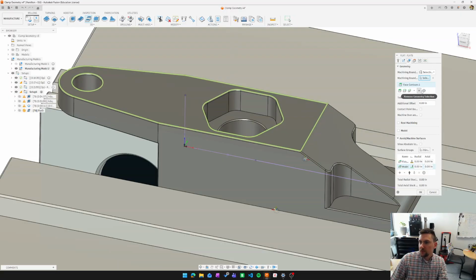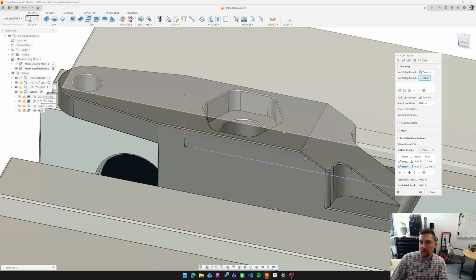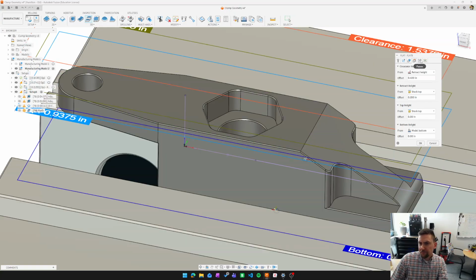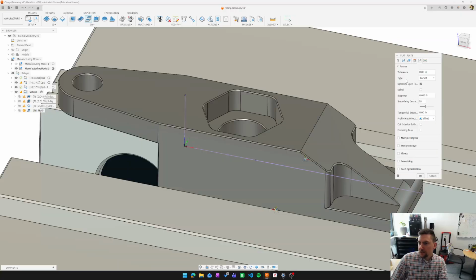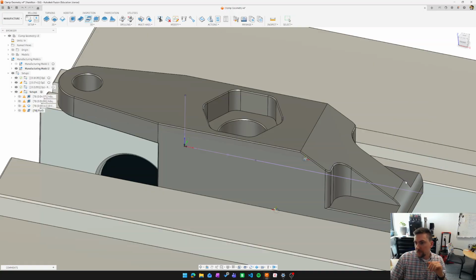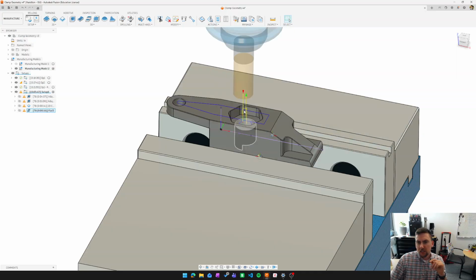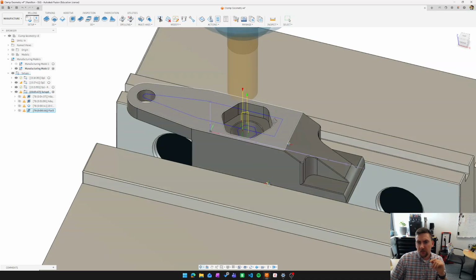No, I just want to do this contour. I don't want to do the face contour. I just want to do the entire surface here. Yeah, and step over here. Let's set tool diameter times 0.75. We'll throw on smoothing. Click OK. Take a second to generate. Looks good.